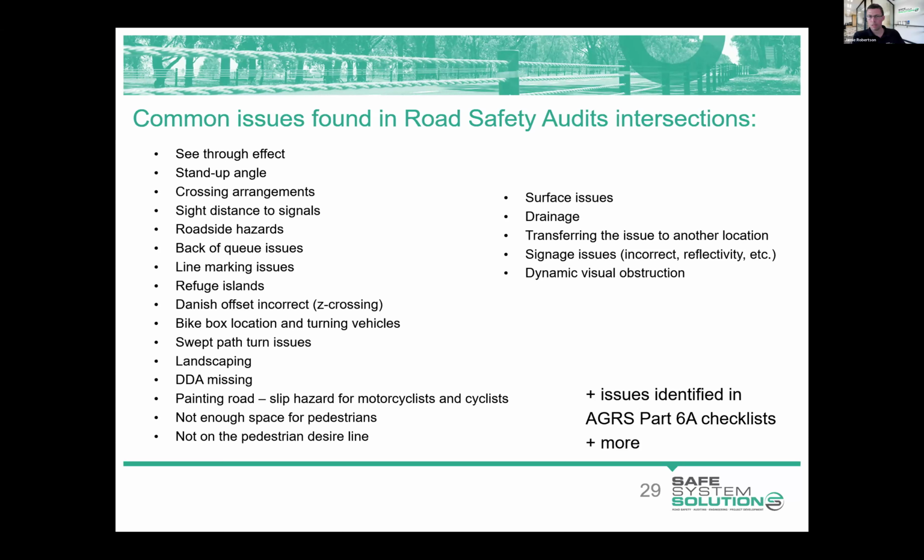Yeah, look, sight distance requirements at signalised intersections are the same as at any other intersection. I guess the idea is that we're providing for the situation when the signals might not be operating. So we need to maintain safe sight lines.